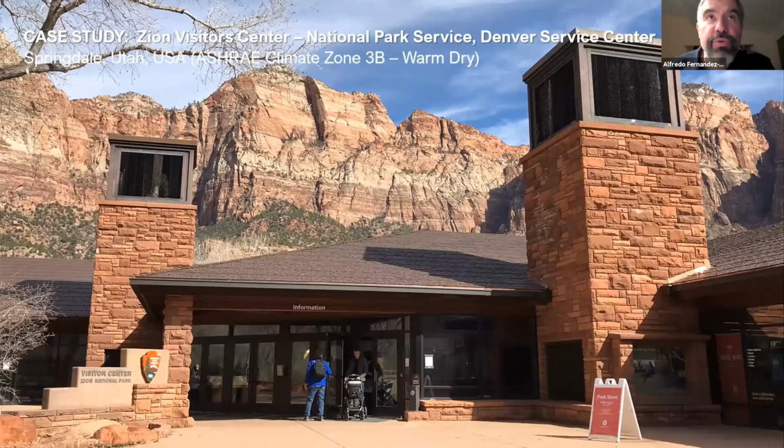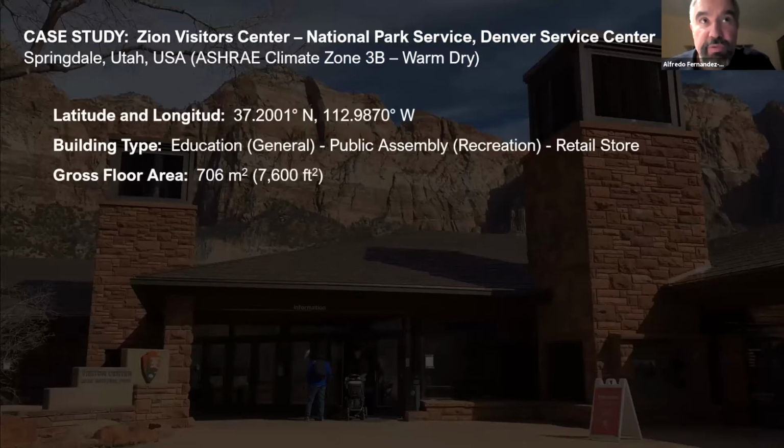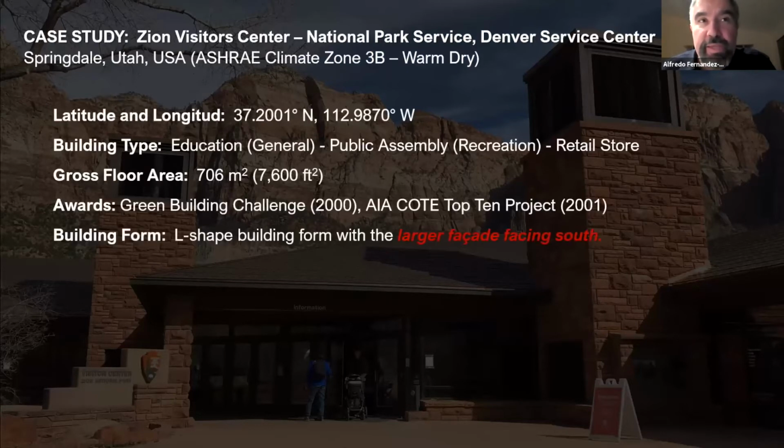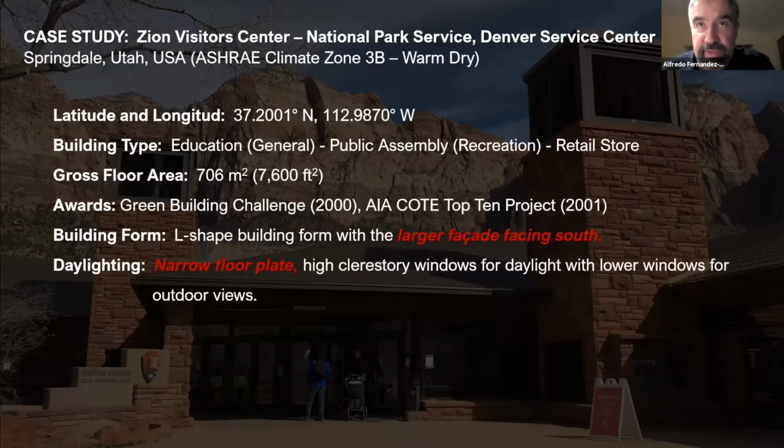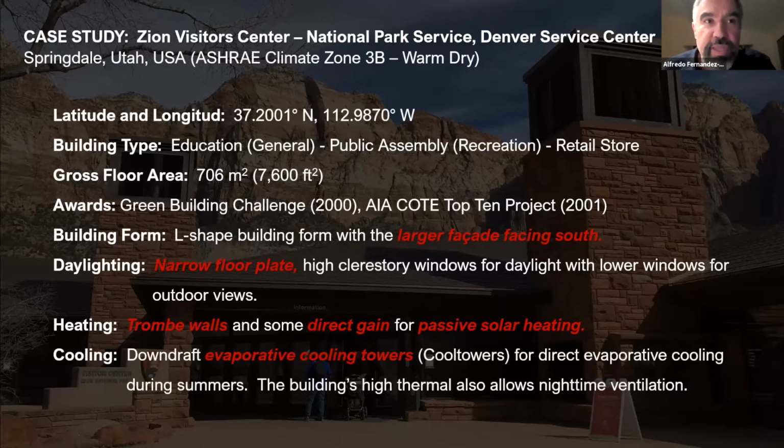I would like to present to you a case study of a building in climate zone 3B of ASHRAE. It's a warm dry. This again is in the United States. And these are some of the particulars of the building. The L-shaped building has larger facades exposed to the south. It has a narrow floor plate, as we have described before. The use of high clerestory windows for daylighting. In terms of heating, it uses Trombe walls and some direct gain. And in terms of cooling, it features downdraft evaporative cooling towers, which we will call cool towers. And cool towers provide direct evaporative cooling during the summer.